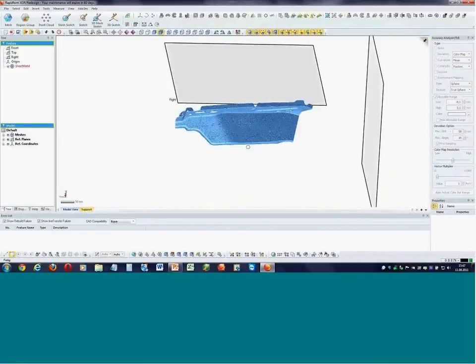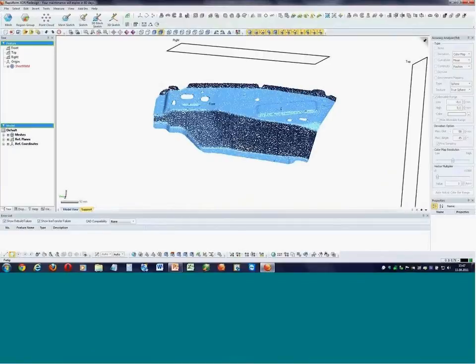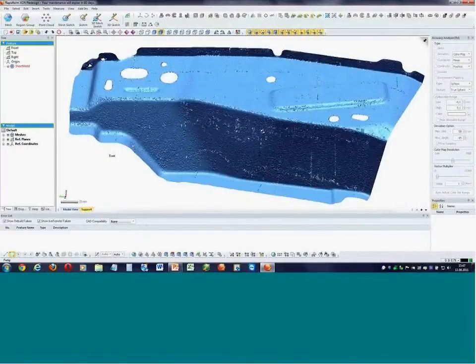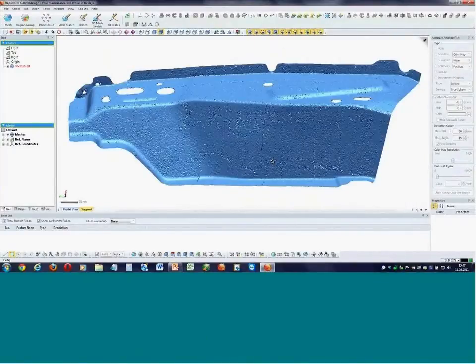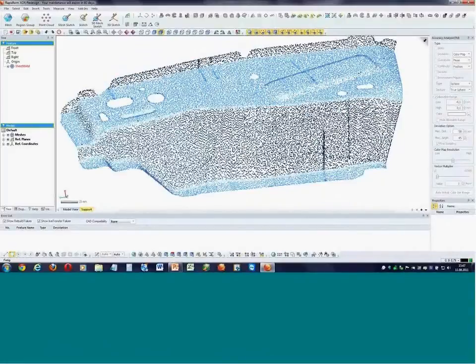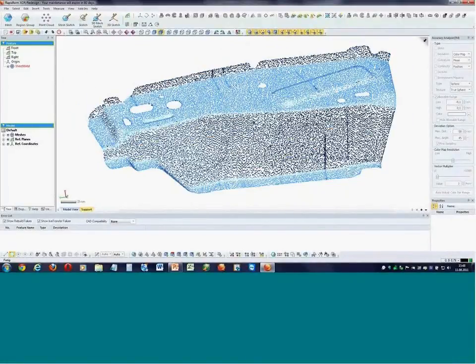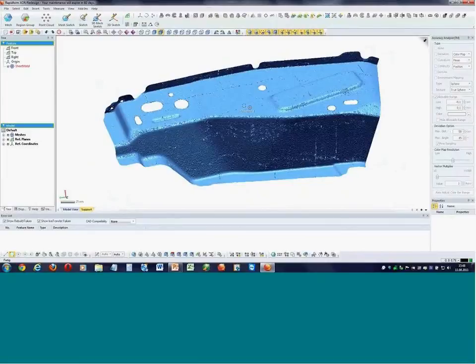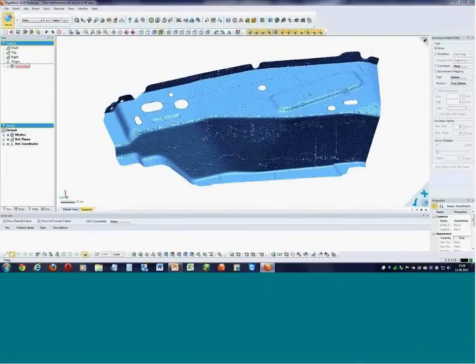Then you can see this could be sample data with a line type laser scanner. This scan data actually has much noise. And now you can just clean up that noise by double-clicking the scan data. And we have several functions to do this. For example, we have a healing wizard, or we have here an enhanced shape function.